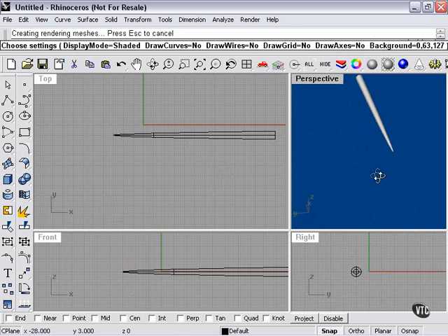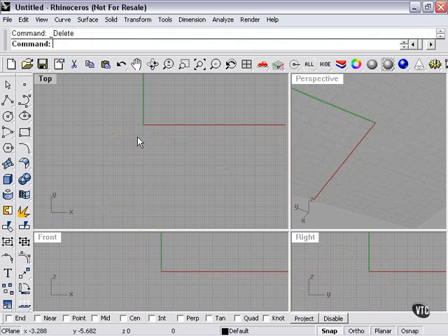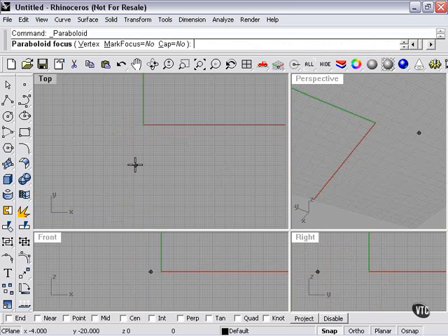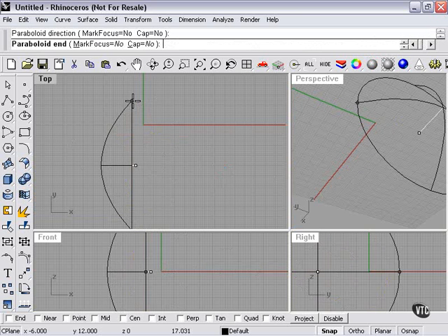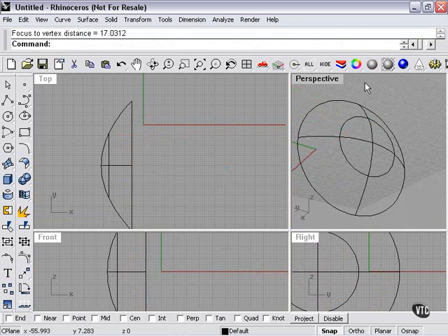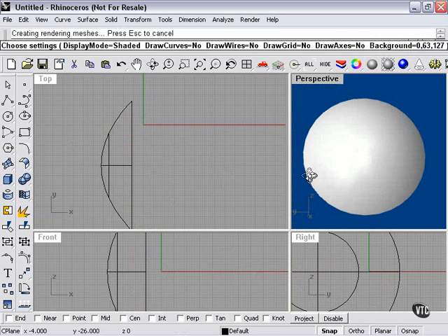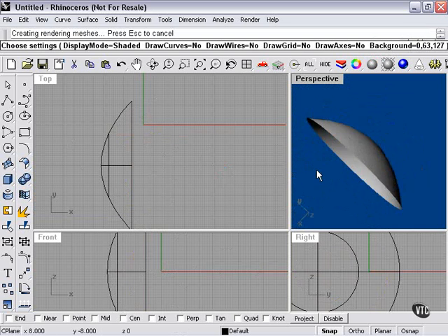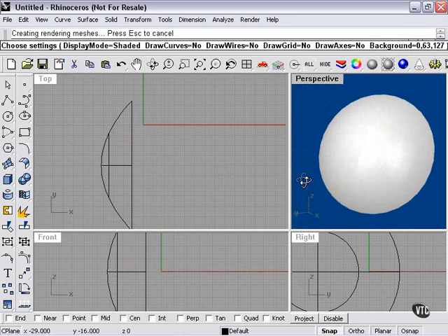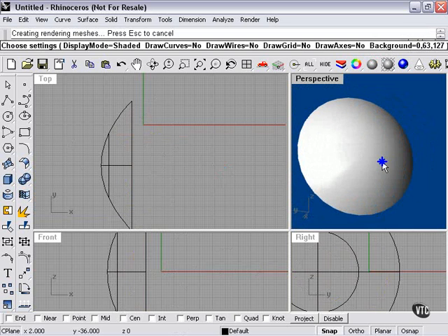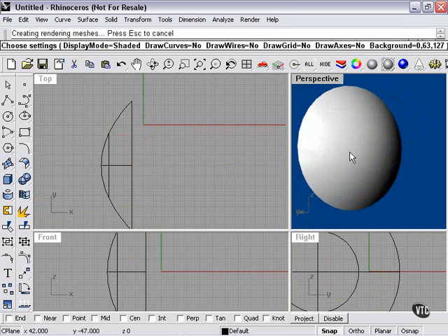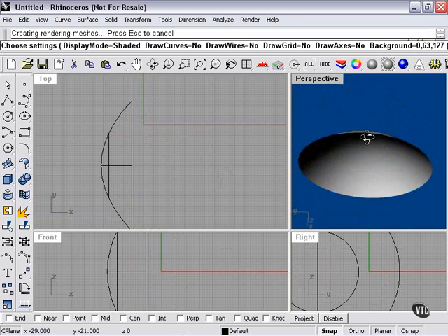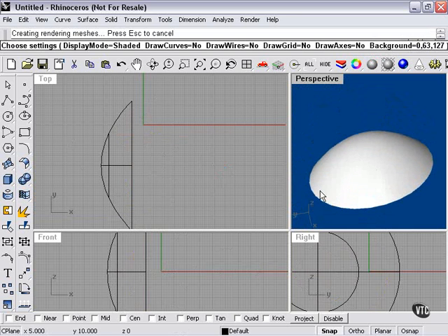In Rhino, it's somewhat complicated to create a shape that actually ends in a curve. In other words, to better demonstrate that, we'll do this. This shape has a very smooth ending to it, as you can see here. It's like the inside of a sphere that's been cut off. Well, a paraboloid is a very useful way to create that shape where using curves might not give you quite the shape you're looking for. It would also be possible to create this paraboloid shape by indeed using a sphere and then chopping the top of it off and deleting the rest of the sphere.